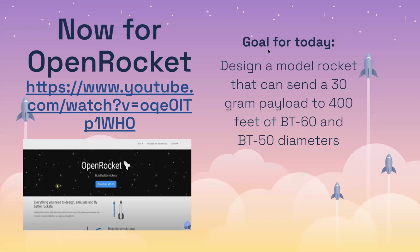So for OpenRocket, OpenRocket is the simulation software that we use for designing model rockets. It allows you to input the components that we talked about in this presentation, and you get to specify what model you want, what size, what shape even, and see how high it will fly given whatever kind of motor you decide to put into it.